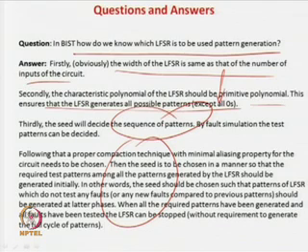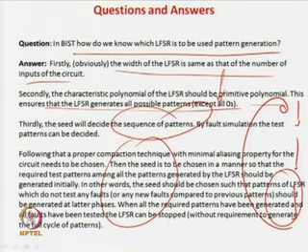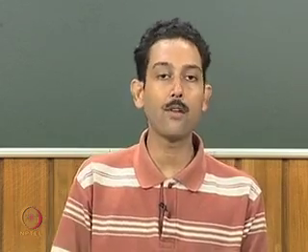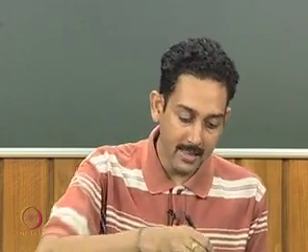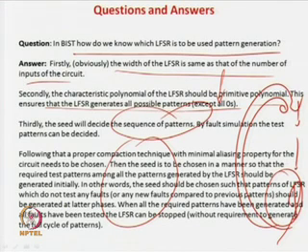Now, again, as I already told you, these are not sequential problems to be decided. Sometimes you have to go back and iterate. Sometimes you find that whatever compaction or compression technique you have used, there is a lot of aliasing because of the patterns you have taken, so you have to go back and require a different set of patterns. Sometimes, for the different set of patterns which give you low aliasing, the area overhead of the LFSR becomes very high. So, you can change the compaction technique. These are the three or four steps which you require to design a BIST architecture or BIST circuit, but these are all interdependent problems and you may have to go for iteration. So, that is the answer to the first question.